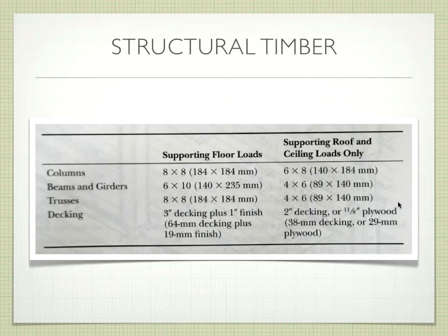Okay, so in terms of structural timber, columns that are supporting floor loads, we're looking at 8x8s. So we're talking big lumber. This isn't little 6x6 posts that are on your deck. We're starting at 8x8 and getting bigger, okay?